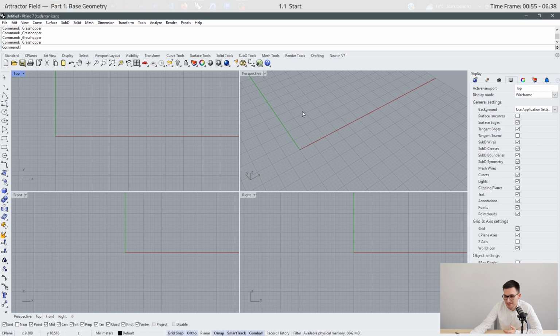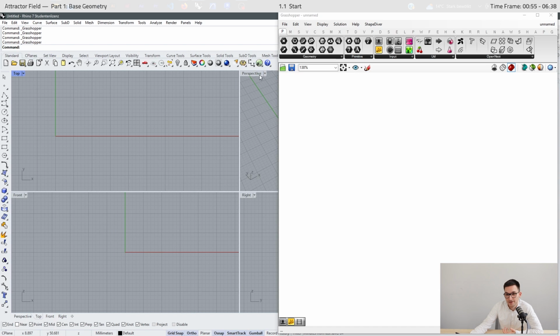We start directly in Grasshopper. Grasshopper can be opened by clicking on the green icon under the Standard tab, or by entering the command Grasshopper right here. And the geometry we want to create now consists of several truncated pyramids, each with 4 visible faces. And the pyramids have a square floor plan, so we can create a grid of rectangles.